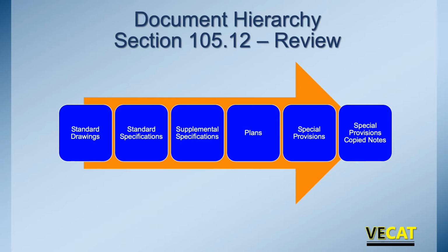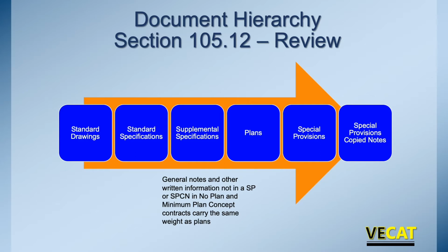So as you open up your contract documents and read through them, see what special provisions and copy notes exist, what special provisions, are there any notes on the plans? Because there can be some notes in here that, again, carry more weight. So be very familiar, and it's very much recommended during your pre-construction conference you talk about these things to make sure everybody's on the same page.